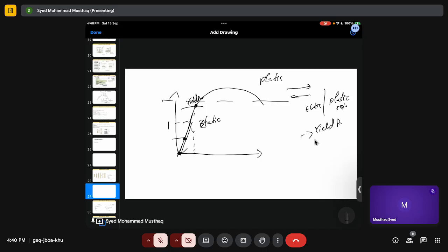One is the yield point, where the material starts yielding, that means the material starts deforming plastically, and there is this point called 0.1% strain. That means once you start this point, this amount of strain is not being recovered. There are different names. So it's best to, for now, just take the yield point as our differentiating point between the elastic and plastic regions.